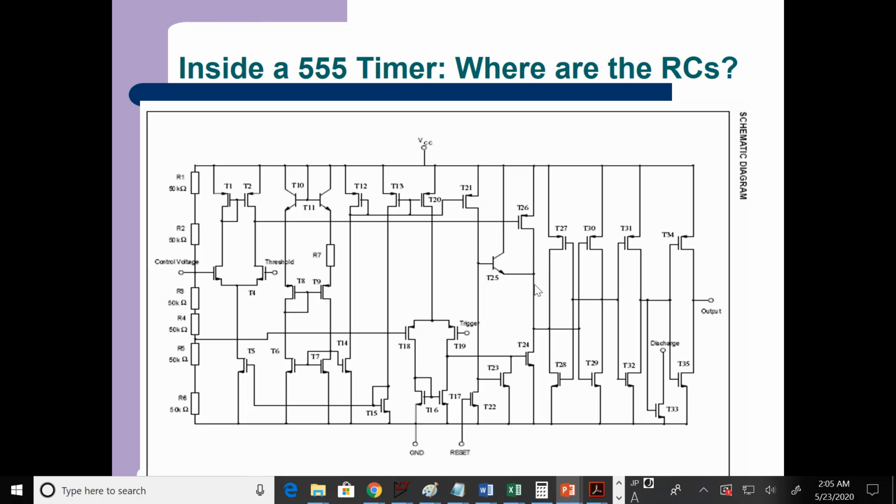But the wires contribute capacitance, transistors contribute capacitance, wherever this is connected to contributes capacitance. So there's actually a bunch of capacitance on this node. It's not explicitly drawn into the figure. It's parasitic. In other words, you don't want it. Be nice if it wasn't there, because then this node would change infinitely fast. But there's capacitance on this node.